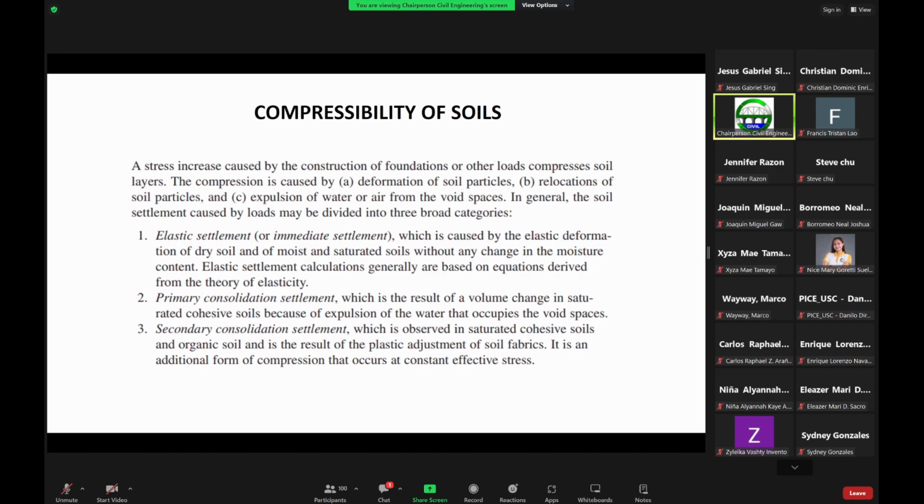So when we prepare geotechnical reports in the determination of the soil bearing capacity needed by structural engineers for them to design the foundations, we try to provide the bearing capacities based on shear failure criterion as well as this one here, the settlement criteria.